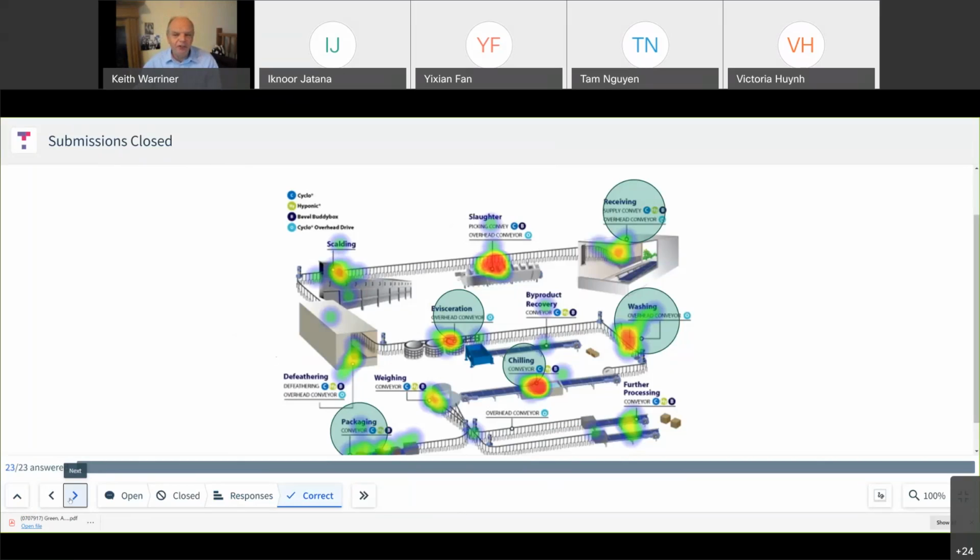So you go through the decision tree, you identify your critical control points, and then you've got to find your critical limits. Critical limits define your critical control points under control. The obvious ones are time and temperature. The temperature of the pasteurizer doesn't go below 20 degrees C for a certain amount of time. And when it goes out of those limits, you've got to have corrective action to get it back in. What do you do with the product that's gone through? Do you rework it? Do you divert it? All written in the plan. You don't need to go running after your supervisor, because you want to control it as quickly as you can and bring it under control.